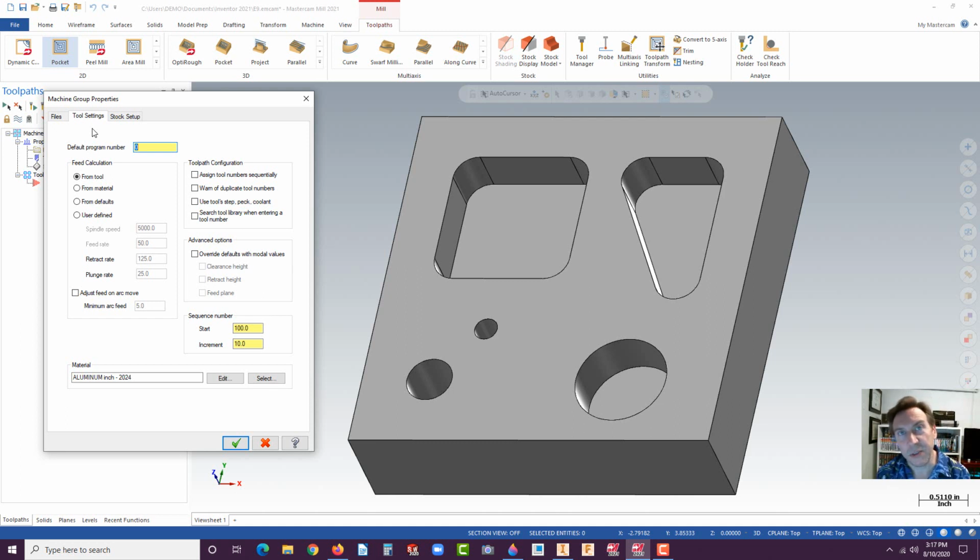You could look them up in the machinery's handbook, depending upon the material type, and it looks at your drill or your tools, like if it's just tool steel or if it's actually coated or whatever you're using. It can vary greatly. Of course, coated tools can go a lot faster in cutting. They have longer life expectancies than typical high-speed steel.